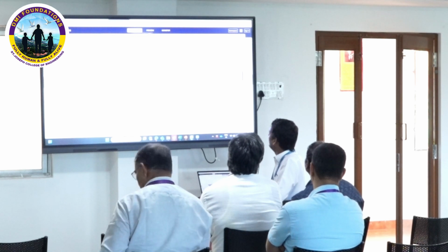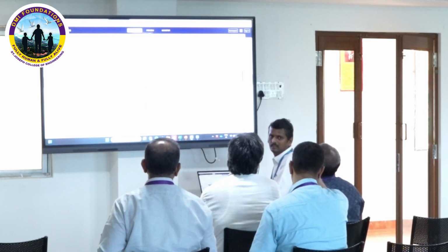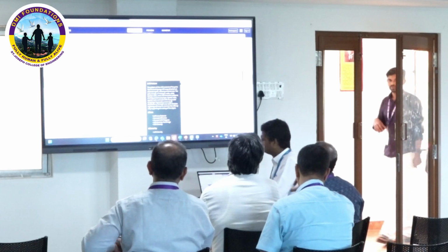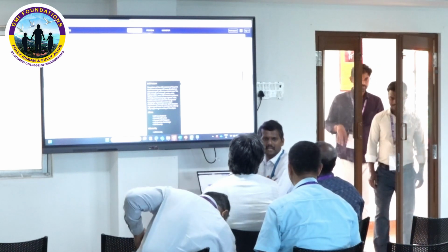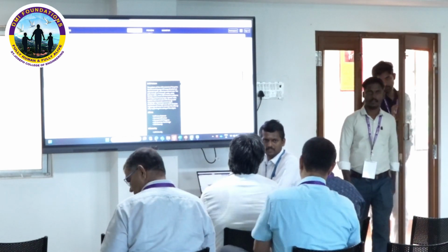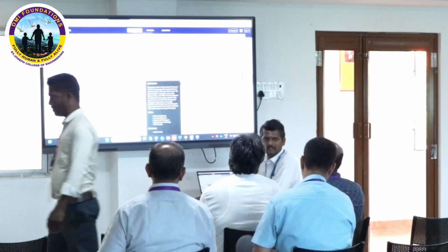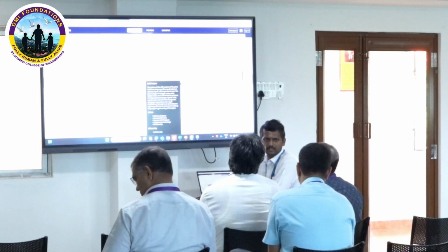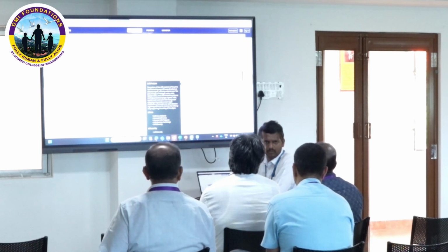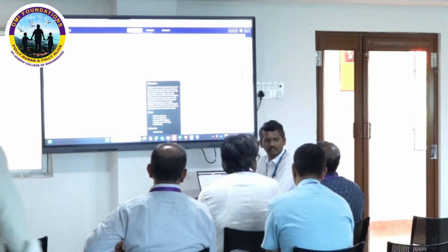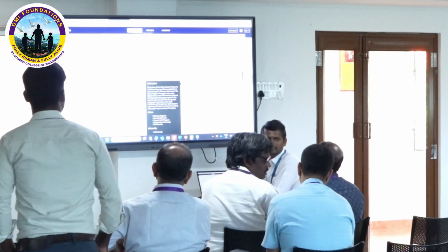Mainly, changing the standard is there, sir. If it is a draft part, or used just for visualization purposes, you can give 10% infill. If it is a little bit of a functional part, but it is not going to undergo any kind of load, then 40% maximum.